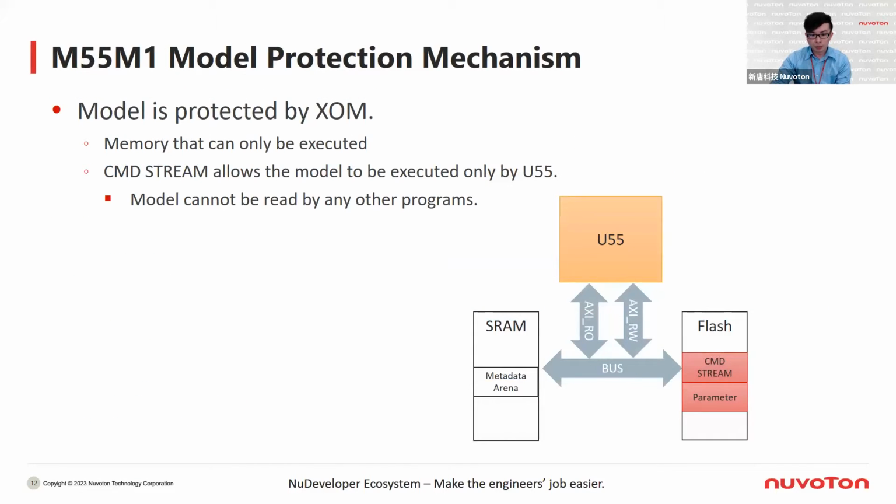The M55M1 uses a method called XOM for model protection. XOM is a special area that can only be executed, not read or written by other programs. We use our Vela compiler to place our command stream into the flash memory.